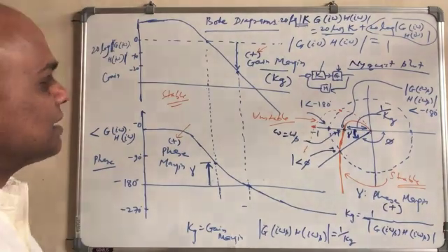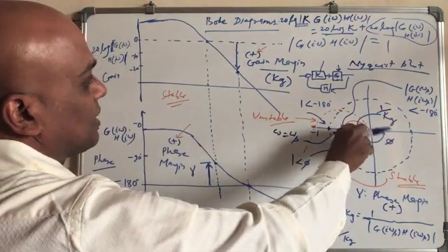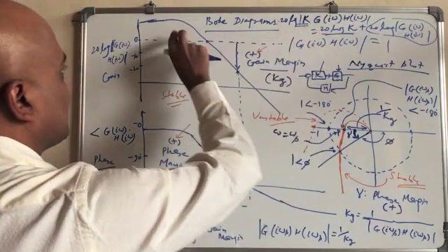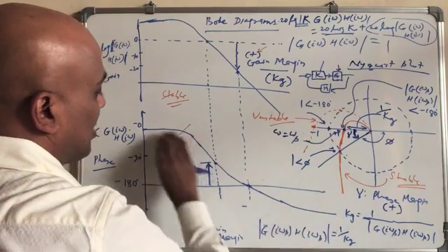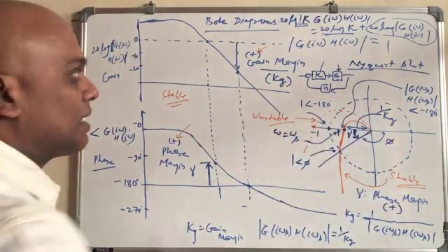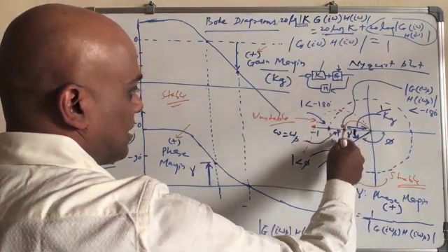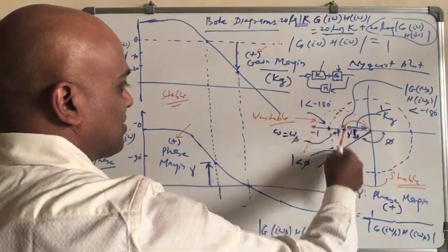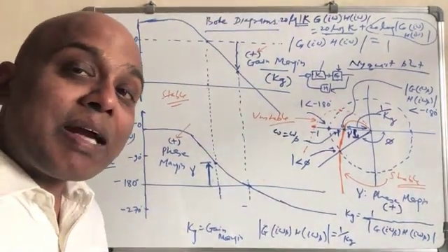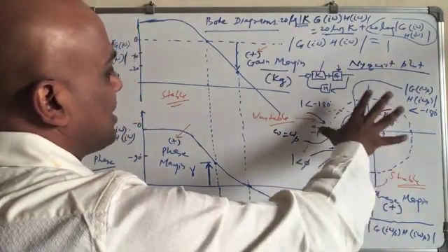Similarly, the effect will be, if it goes up and down here, the curve will change here also. Just introducing k here, this will not change because the phase remains the same, this will go up and down. But what will happen to the Nyquist plot? If you multiply k with G(iω)H(iω), and the original Nyquist plot is this one, how will the new Nyquist plot look? The effect will be just zooming in or out, meaning that the phase remains the same as earlier.